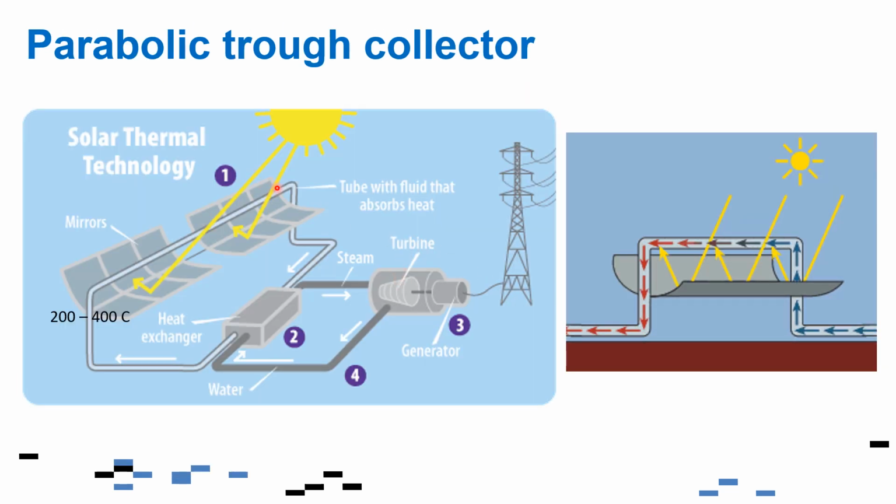So the parabolic trough, as I mentioned, has a collector, a concentrated collector here. So the liquid is actually recirculating towards this part, and there is a heat exchanger, wherein the heat exchanger contains water on the other side that could heat up and become steam, and this steam powers the turbine here.